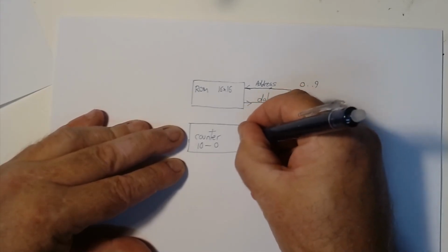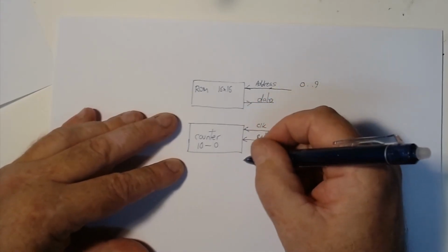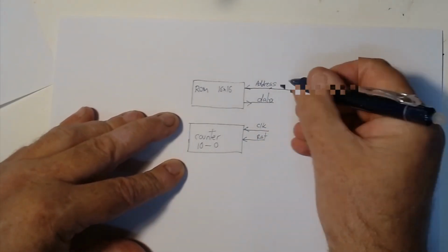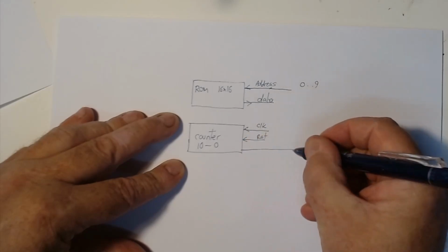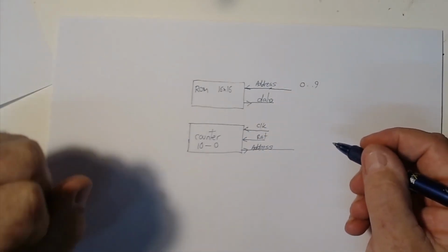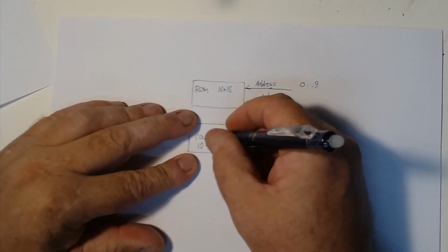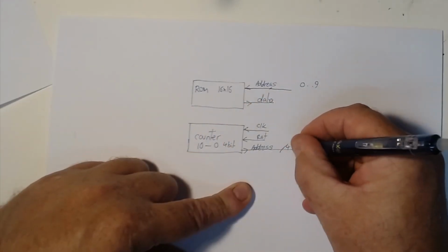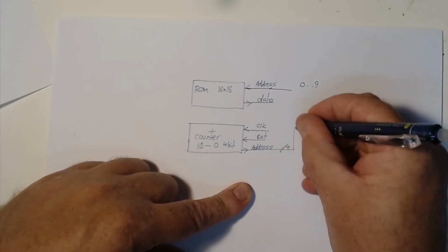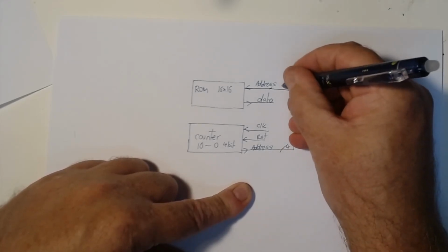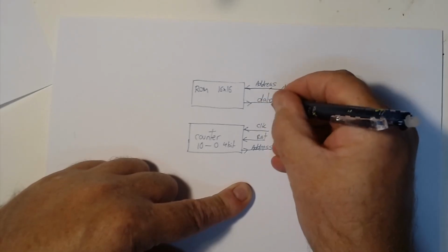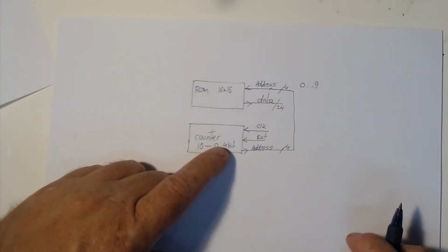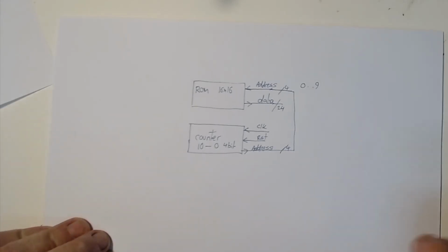So they're both inputs, and the output from that can actually be used as our address up here. So this one would have to give us a 4-bit output, /4. So that shows me that I've got 4 wires, which will go up to here, which is also a /4, and my data will be a /24 for 24 bits of data.